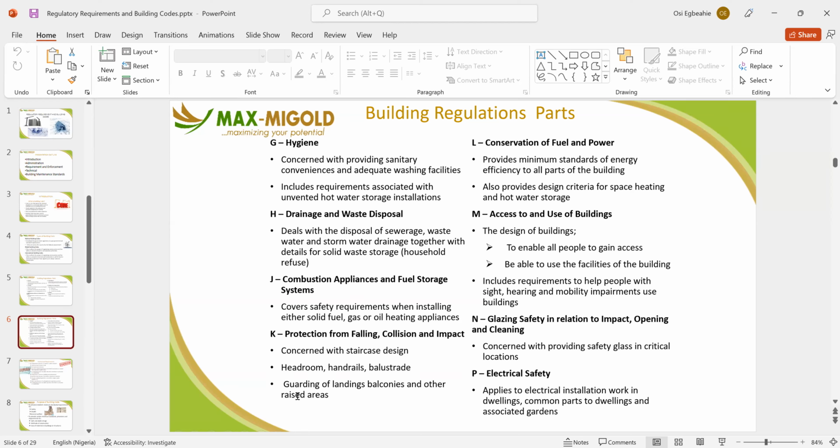If they even want to give a little bit of consideration, it must be something around 1050, which is 1.05 meters. That's the consideration they give if that is not possible. But that's the minimum of what they require to ensure that the staircase can take a normal human being and will be able to move. And the basic requirement for risers is that the risers are 150 while the treads are 300.